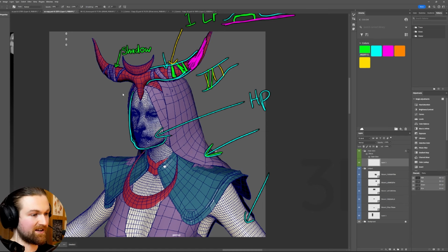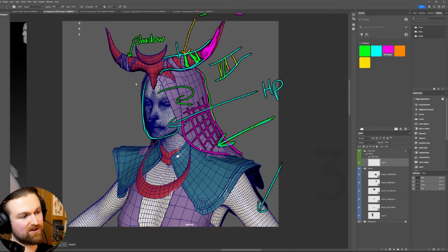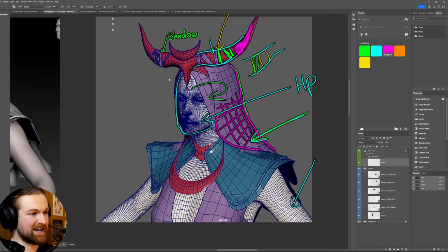Now with this area, in terms of the cloth, we've got a lot of curvature, and because it is cloth, if you imagine during the animation, this head will be rotating. So the animator is going to need lots and lots of vertices. I really suggest getting two wins out of this. The first win is that the silhouette is going to be much nicer for the curvature of the cloth. And then also when it comes to the simulation, we're going to have slightly more options. So just increase the resolution of this area. It's going to support you a lot, especially in areas of high deformation, and also reduce the main polygon count of the character.